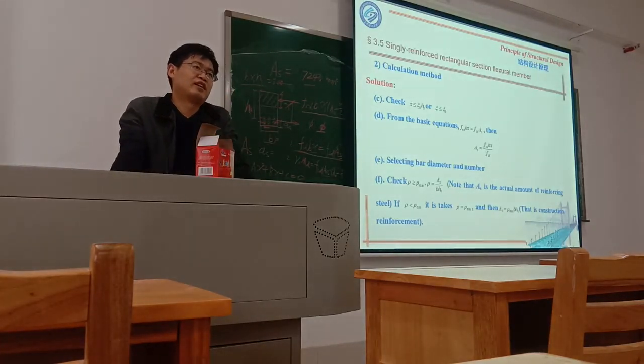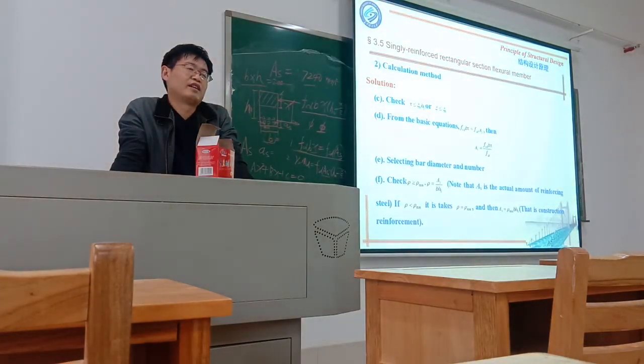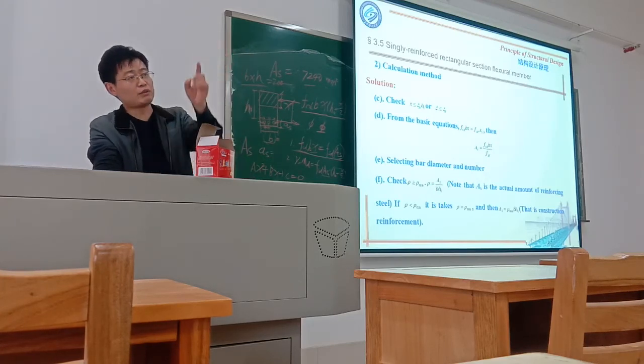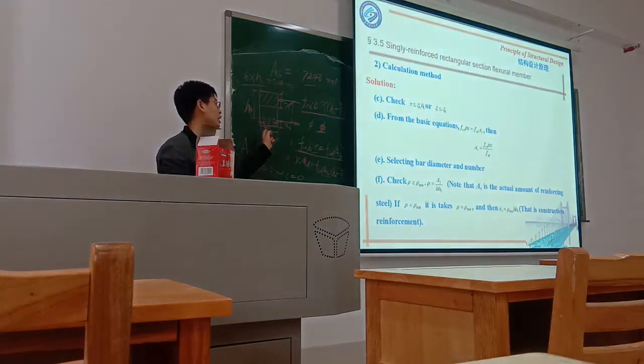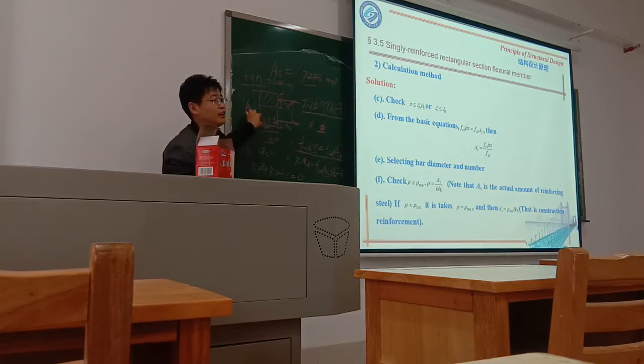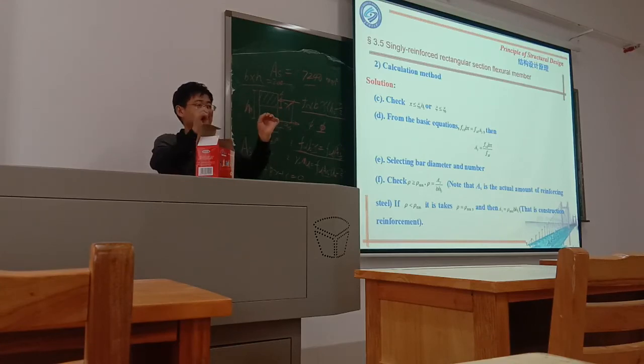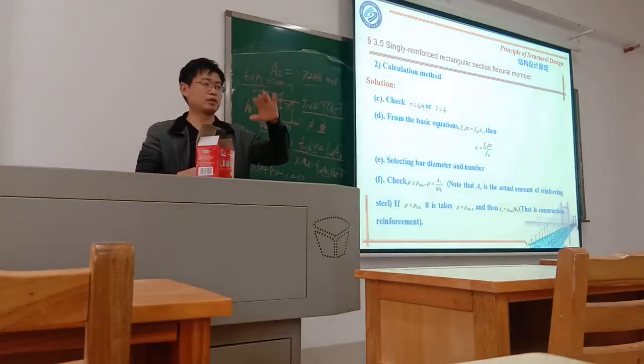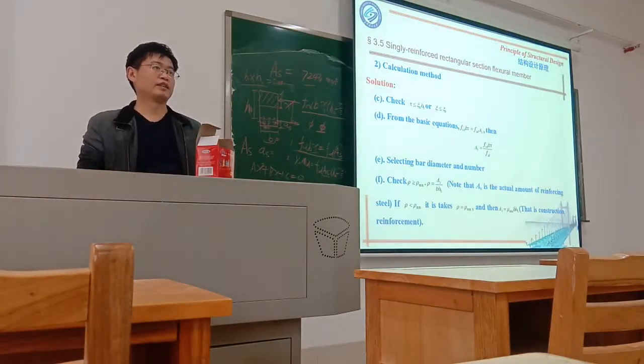No, when you choose this one, 32 must be down. The first layer must have the greater number. Normally it should be like this. If you have to use this design, you can use 532 at the first layer and maybe plus 1 or 2 25 in the first layer. Normally the number of reinforcement bars in the first layer cannot be smaller than in the second layer.